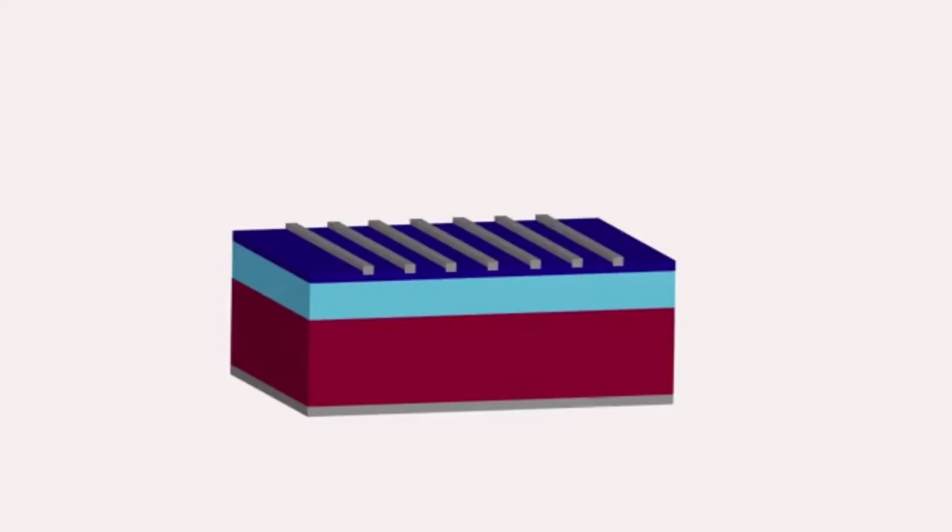Let's see what this looks like in the cross-section of our solar cell. As we work down from the surface of the solar cell, there's a top anti-reflective coating. There's also the top contacts that will carry the electricity generated from the silicon out of the cell and into the circuit. Even though we're showing them as two layers, the next two sections are actually one piece of silicon.